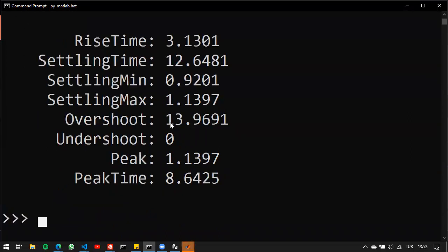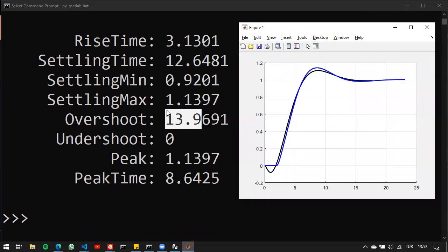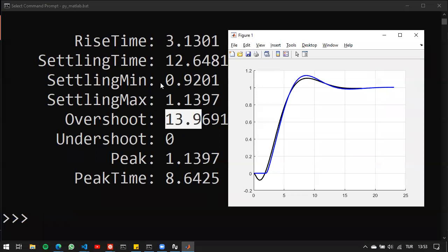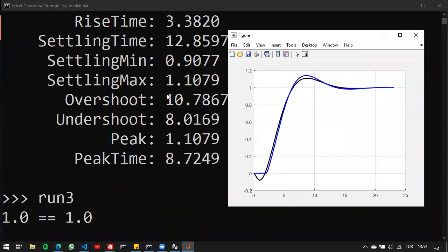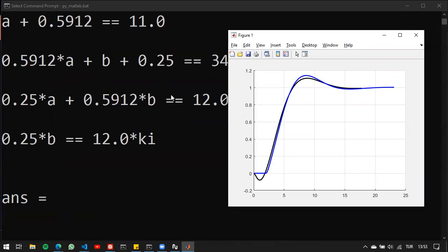So here I can see that the overshoot value is not, again, 10%, but it's 13.9, so roughly 14%. Of course, for now, I'm okay with this, but it might be the case that I'm looking for exactly 10%, then I might maybe improve it a little bit. But, well, basically using this approximation, since I have 10% here, I cannot improve on that. What I have to really do is increase the Padé approximation, the order of that, because a higher order means better approximation.